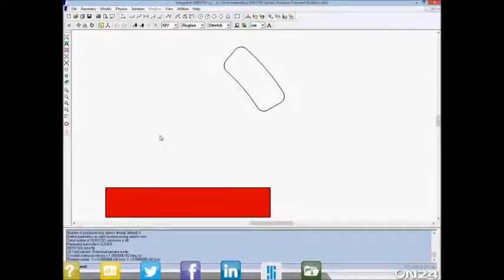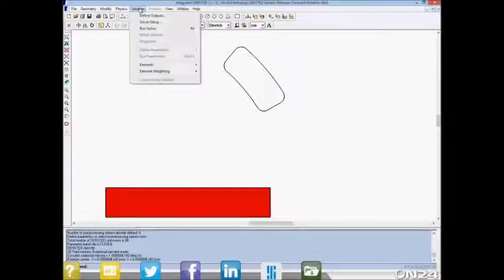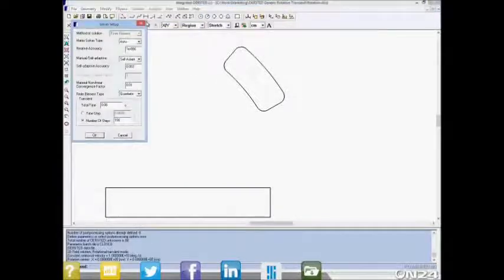So with this configuration, the solver is going to, in time steps, move the magnet into different angles of rotation, and it will track the changes in the flux from one step to another. By doing that, we get the time-dependent behavior associated with the motion of the magnet. So in the solver setup, we can see that there is a transient with a total time given of 0.06 seconds, and it's requested 100 steps to be taken.